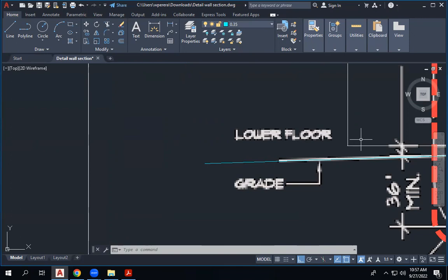Still, it's an issue. Sometimes the structural engineer issues drawings saying this is the floor level. But in architectural drawings, the ones that we give, it says finished floor level, because we are not referring to any structural elements. So there is a difference. The contractor will definitely finish his structural floor slab at least 2 or 3 inches below our level, because we need that portion for the finishers to level it and finish it.